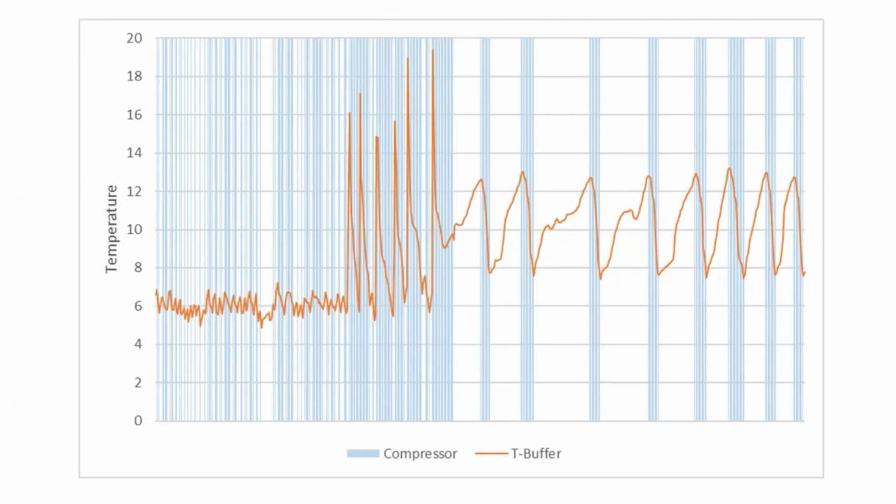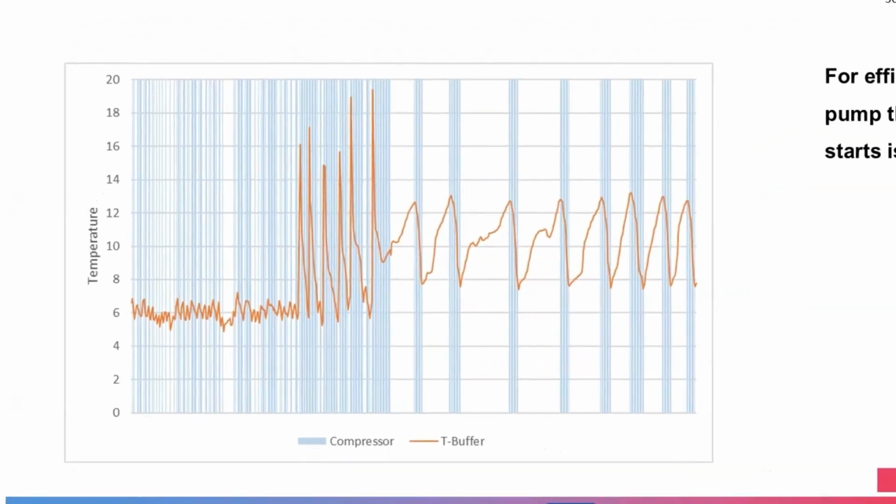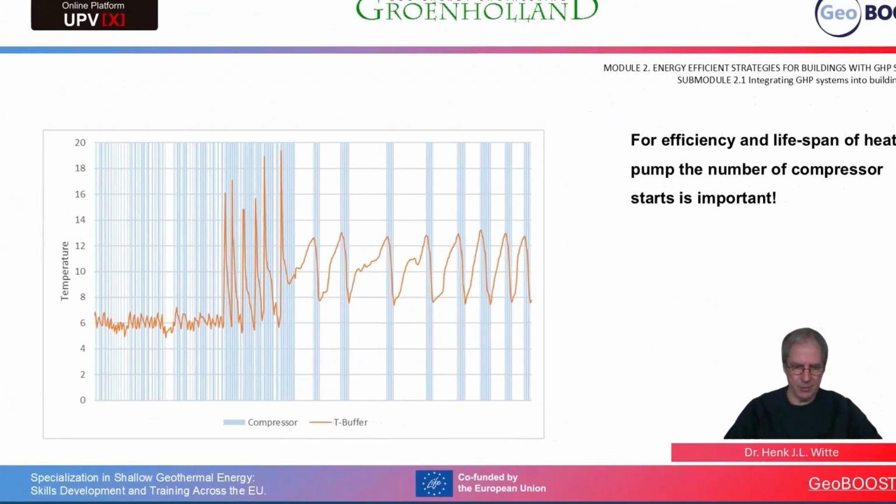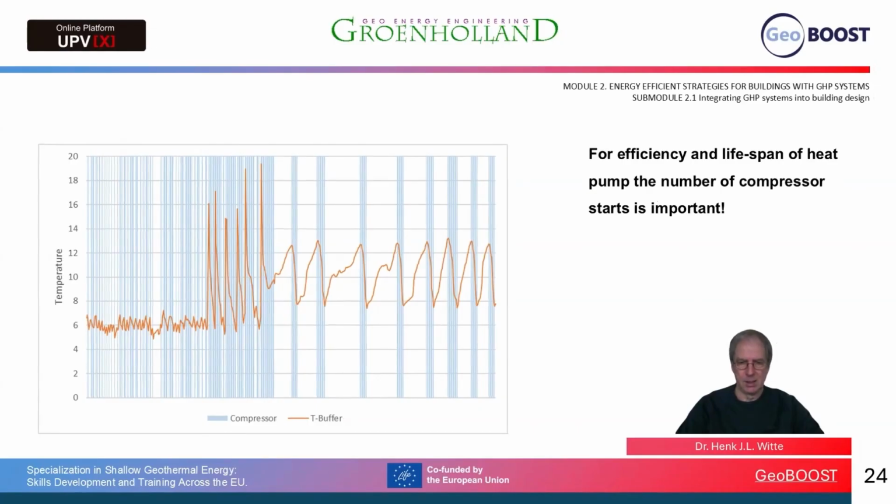However, if we did this and also increase the set point from 6 degrees to around 10 degrees, we can see a huge improvement of the start-stops on the compressor, and also the behavior of the whole system in a thermal way is much better in this case.